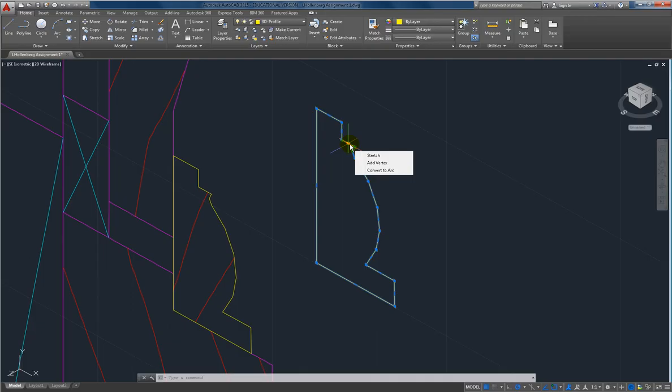You type in pedit, then M for multiple. You select all the multiple pedits. It asks you then, do you want to convert the lines into polylines? You hit enter for yes. Then you hit J for join. Then fuzz distance comes up, and usually if you just hit enter, it works. And then it'll close the fuzz distance.